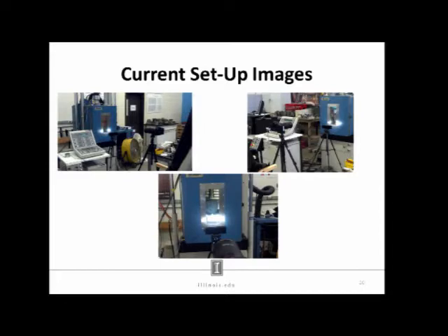But essentially this is just our Instron controller, the cooling chamber. I have an LED light set up outside. It is kind of pointed at an angle. I have the camera directly perpendicular to the surface of the specimen. I make sure I use a level every time, making sure that I don't have any angle to the camera face.